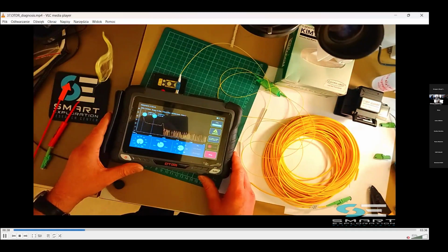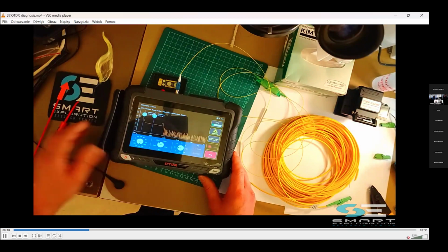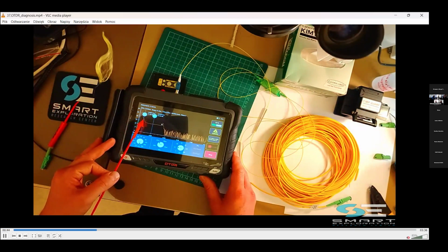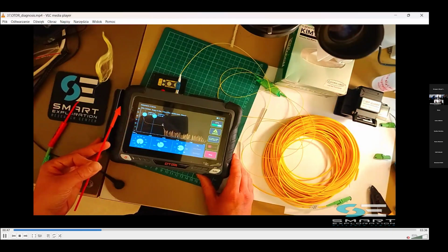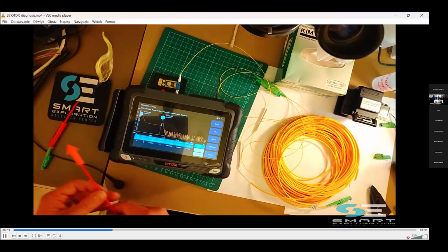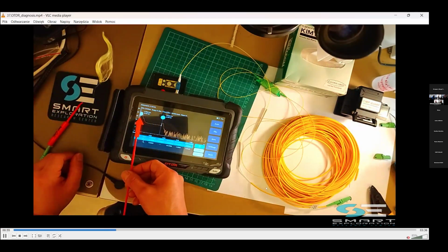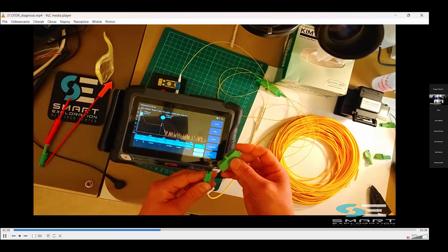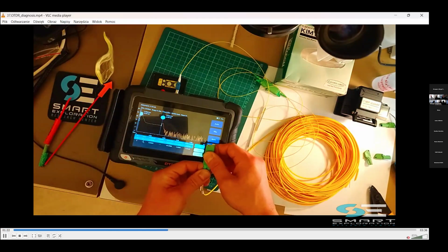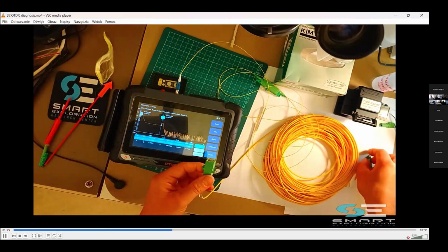And we can observe, yes, this cable is done properly. We have low attenuation. The reflection over here is because we have not terminated the cable. We have just a connector on the end, so we have some additional reflection. When we terminate the cable, we can do that very easily with the female connector and the termination tip.